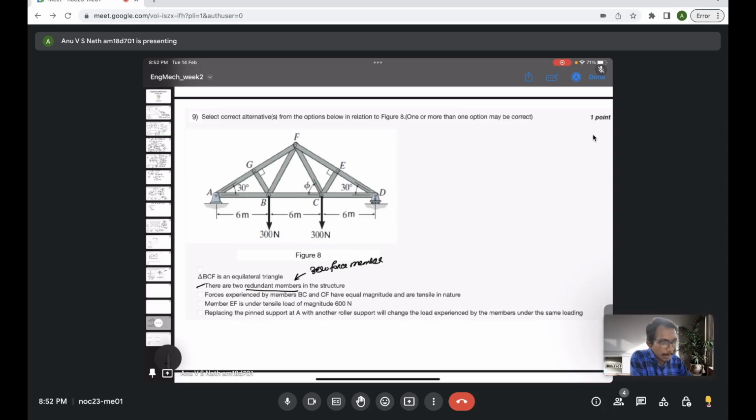No, sir. So basically, if you have a member, you will have equal and opposite forces, either compression or tension, acting on it. So net force will be zero always in a member. So if I say BF, net force will be zero. But just that it is acted on by equal and opposite forces on both sides, either compression or tension. According to which, right now we are considering rigid bodies, but this is important in deformable bodies. That is a real case, right?